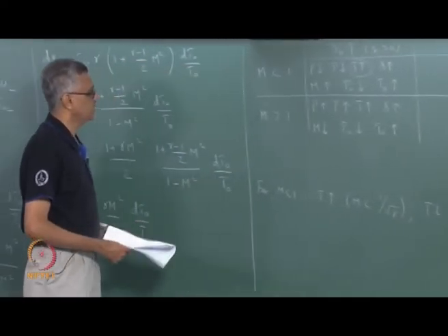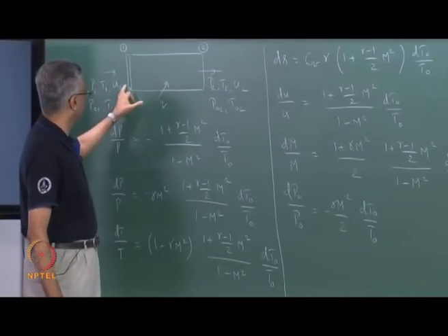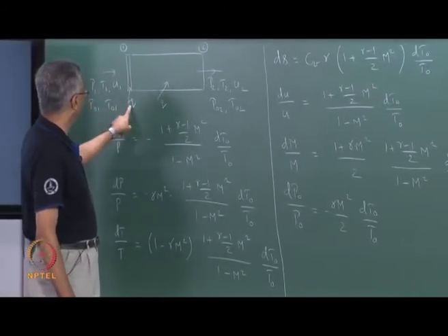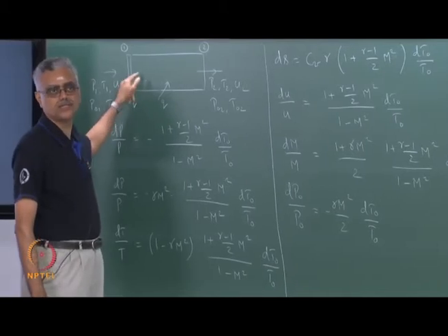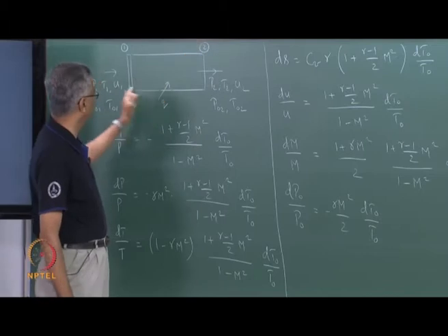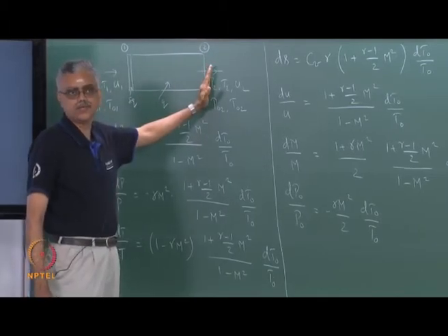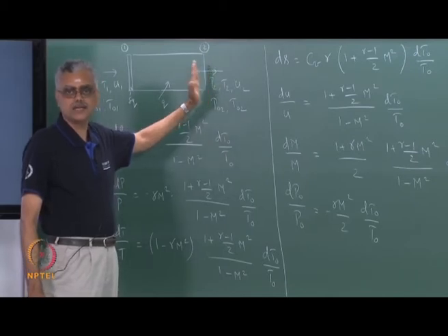What we want to do next is, starting from the inlet state, I want to sketch the process that the fluid goes through. For each delta Q addition, I want to know where the next state point is, then I want to keep track of, I want to draw the locus of all such state points so that we go from inlet to outlet. Okay? This we are going to do on a TS diagram and a PV diagram.